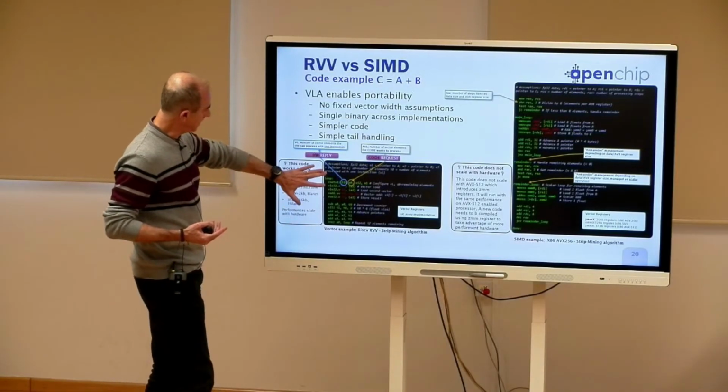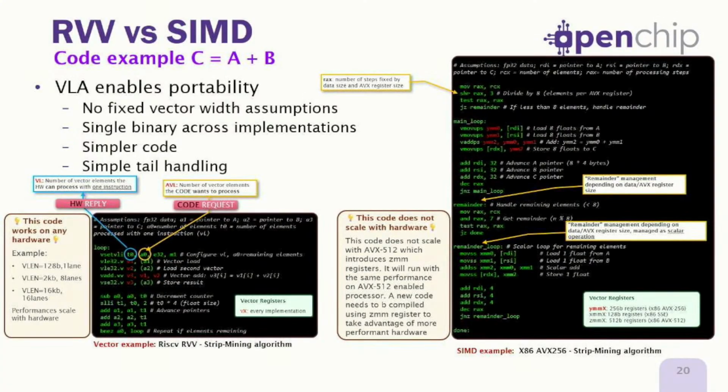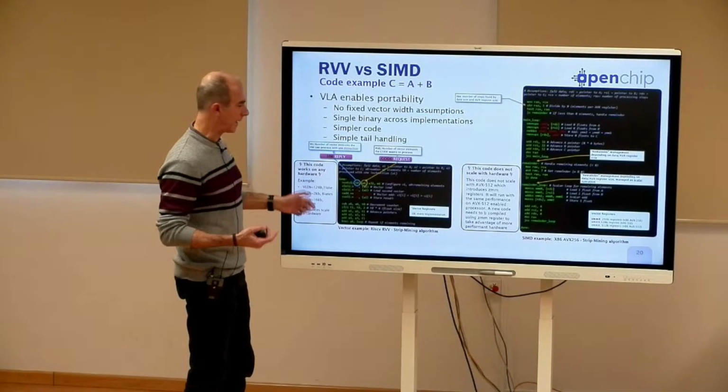So let's see this code. Every kind of vector instruction starts with this instruction, vsetvli, which sets the characteristics of the vectors you are going to deal with in your operation. So if you want to do a sum, before that you have to do this kind of operation every time: you have to set the number of elements, the type of elements, and so on.